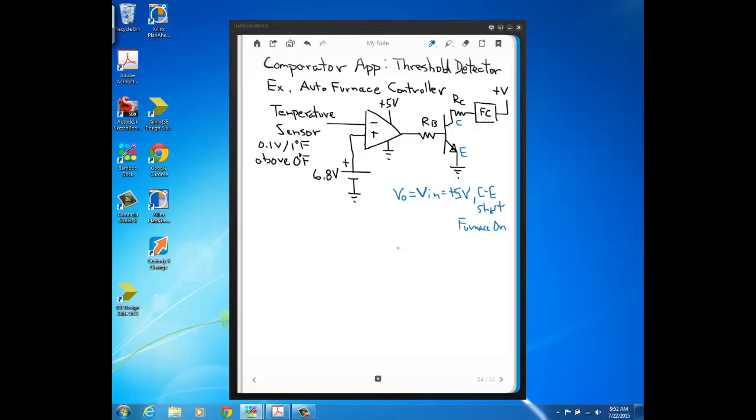Now when V0 is the other possible value, which is 0 volts, ground. We're assuming this is one of those op amps where you can ground the minus V input. So minus V is just grounded to make it 0 volts. That would make the input to the transistor switch circuit also 0, which would make the collector to emitter, or the CE node, act like an open.